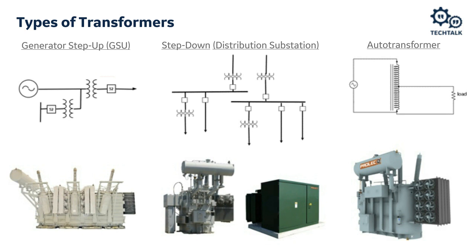Sometimes the GSU will be built into the generator assembly itself, but in any case, whether the protection is combined into the generator relay or a standalone transformer relay, it's absolutely critical to have adequate transformer protection for these.